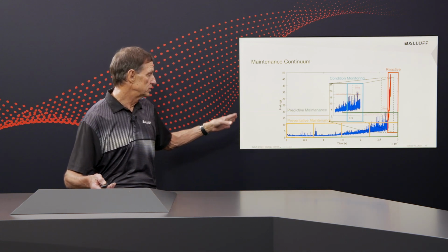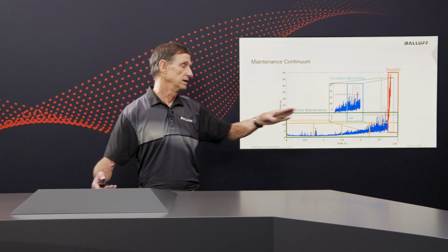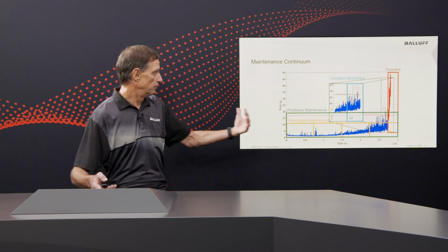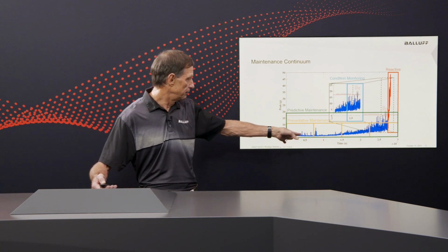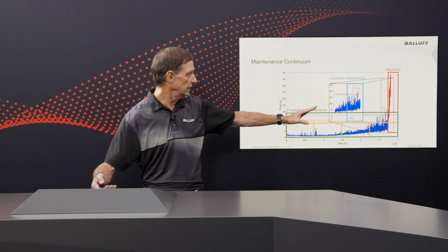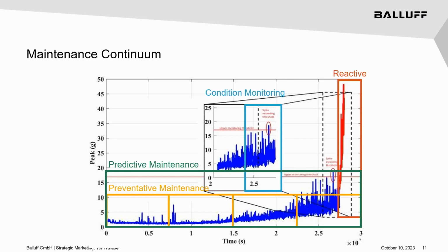The final approach, predictive maintenance, looks at the whole set of data and starts to analyze trends. And just from an outside perspective, taking a look at this, you could probably say about 8 to 9 months in, things are starting to get a little bit out of control, and you can have either people doing the analysis or even use software tools that would probably start to tell you that somewhere about 8 or 9 months into the process, you need to start doing some analysis more deeply on the machine, looking at things and starting to understand what the problem might be, taking action far before that potentially catastrophic failure takes place.